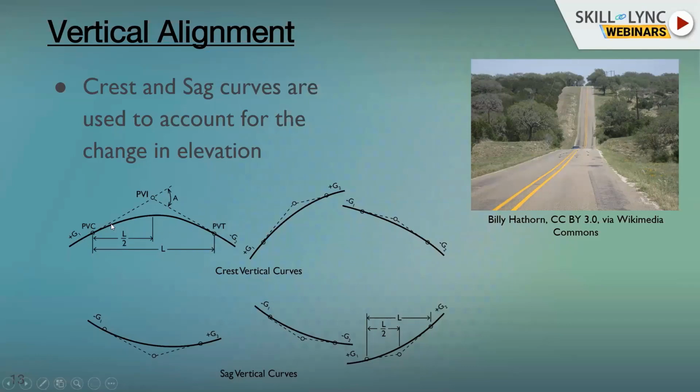If you are traveling at 20 kmph, like on a street road, the road in front of your home, you might not need a flat curve. You can follow the topography and simply go up and come down, because speed is not the criterion on local roads. So you have to be very particular about the design speed and the type of road which you are designing to address these kinds of issues.